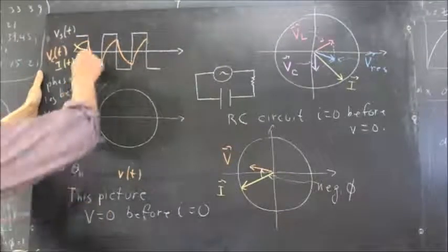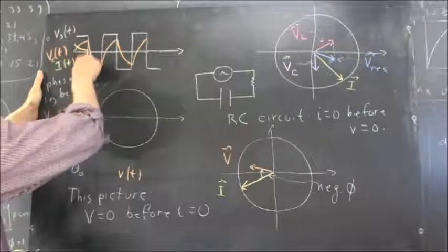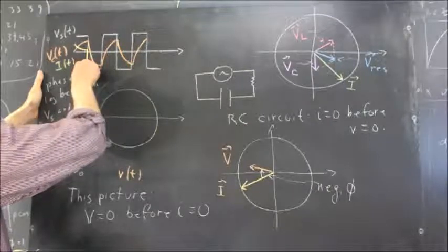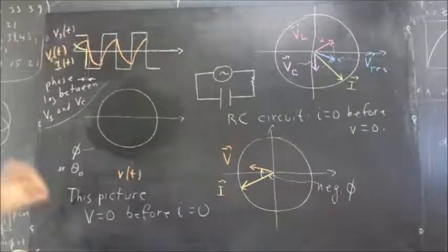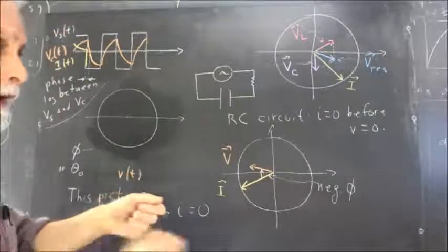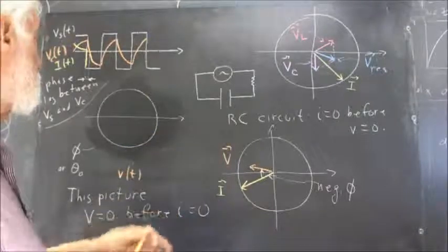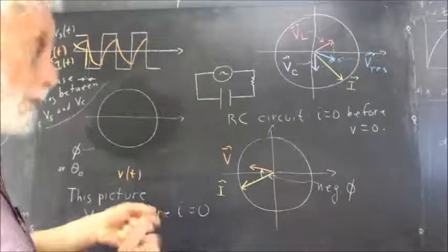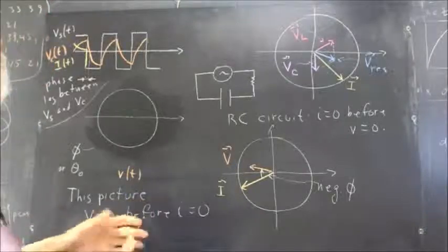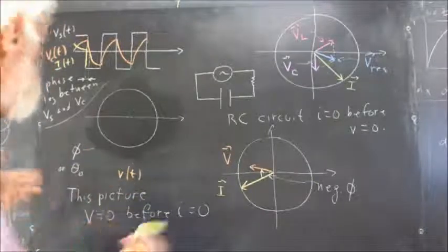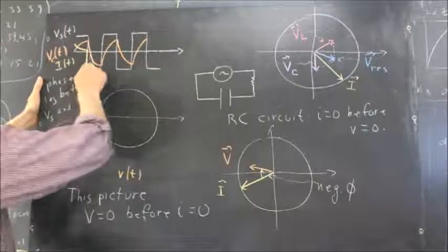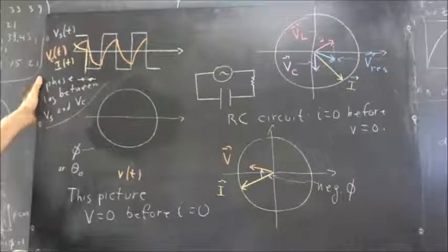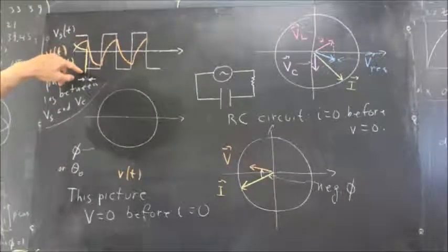So the current is going to go down very quickly, almost instantaneously, down to some low value that's much greater in magnitude than the positive value you had here. And you experience that when you reverse the cranking. All of a sudden, the cranking gets really difficult. The mechanical resistance increases in a way that is surprising if you don't already know what to anticipate. So your capacitor current will go down to some value here, okay?